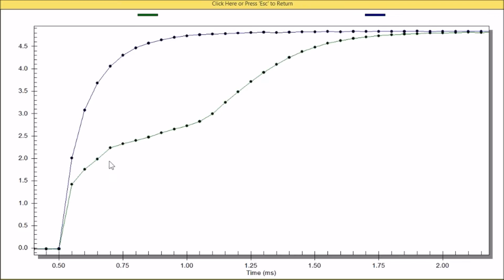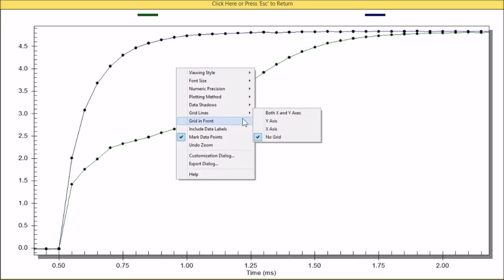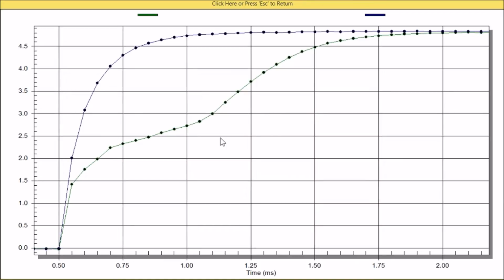Mark the data points. Notice the difference in the output voltage at each point. And this is our memory window, as they say in the IC memory business. Saturation out at this point. Here's my shelf voltage. Here's where the remnant polarization is switching, in this region. Past here, there's very little remnant polarization switching. Here, there's just a little bit. So we're going to stay between these points right here for our memory.